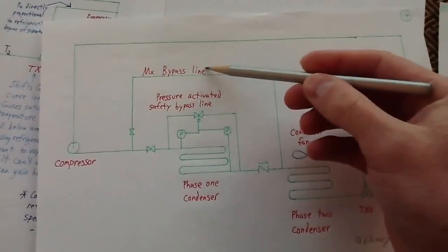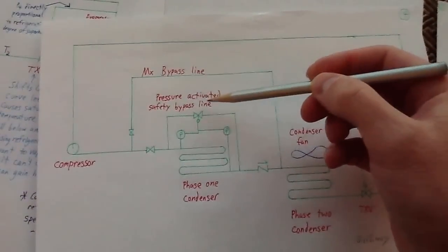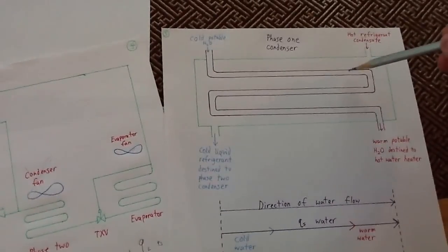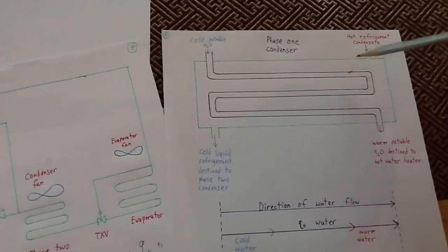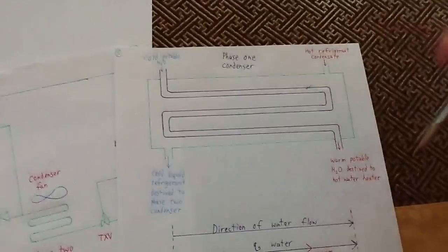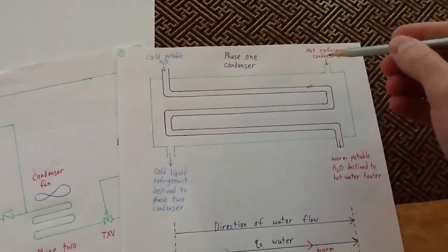So this first line is just if we're going to do normal maintenance on it. This is a safety line right here to prevent these two mediums from meeting up in case that develops a hole in there, or there's a breakage or something like that. Again, we've got to keep the refrigerant out of our potable water. Well, that's what this right here is for.